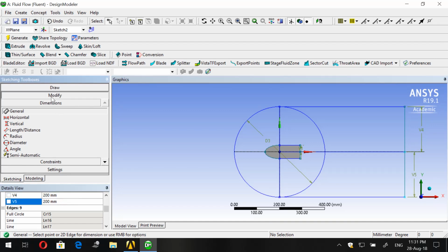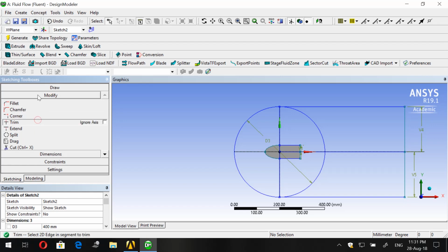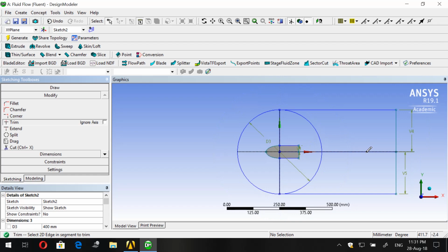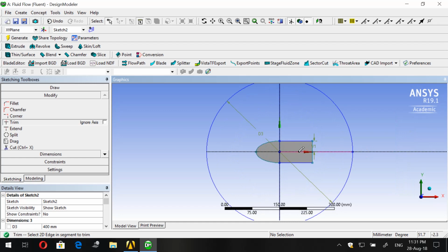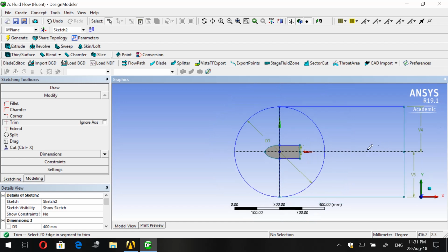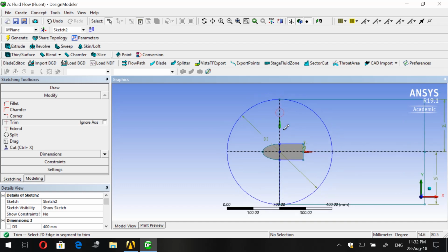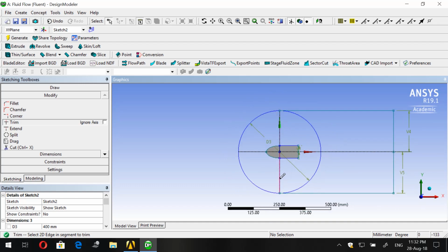That's right. Now let's go back to trim, modify, and let's wipe out the axes that are not needed. So we don't need this, we don't need this. Now I pressed two times because there are 2 edges, because we have drawn 2 triangles, so don't worry about it.